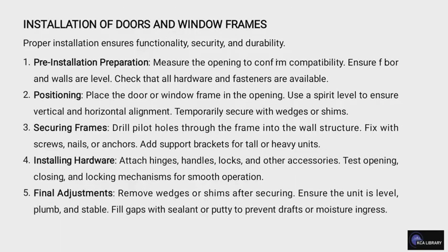Installation of doors and frames. Proper installation ensures functionality, security, and durability. It is important to look at these stages. The first one is pre-installation preparation, where you measure the opening to confirm compatibility, ensure the floor and wall are level, and check that all hardware and fasteners are available.